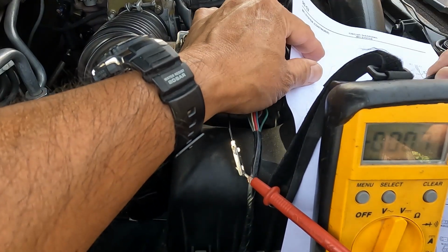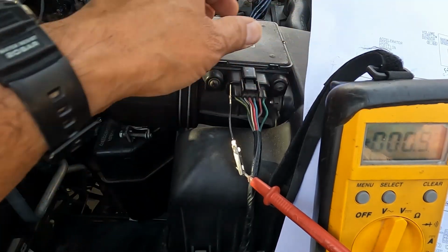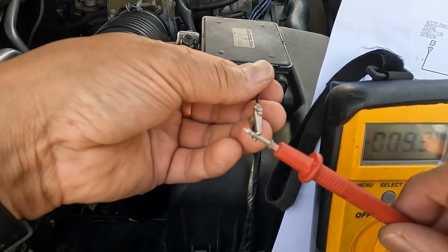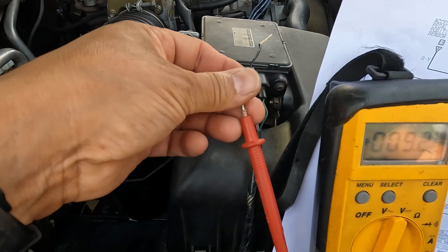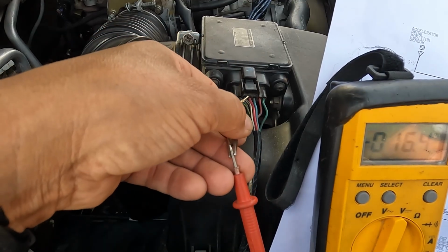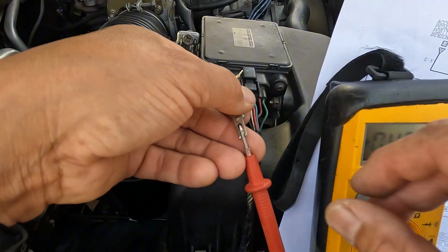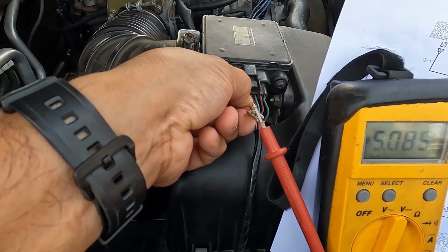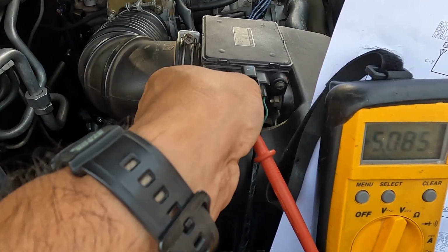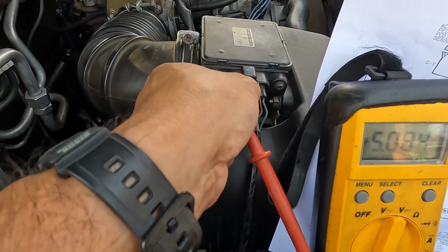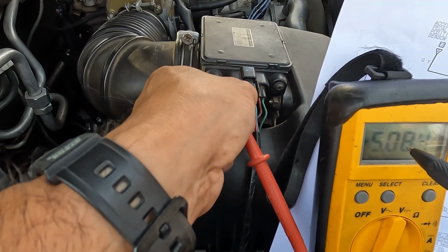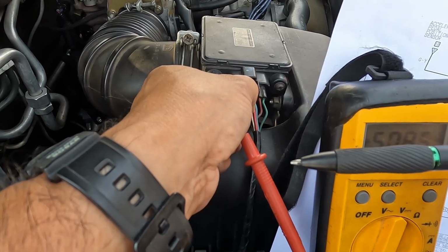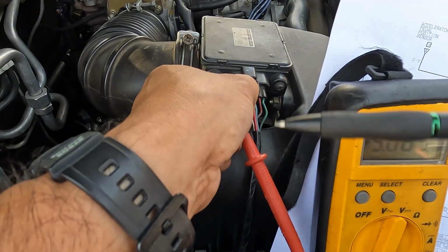The baro, we had said we had 4.0, and we'll go over these on the bench over there. So those are the first 5. Now these are the signal, the mass airflow sensor signal wires. Terminal number 3, which is the white with the black stripe, and that one, remember when I told you guys that's a frequency output signal. So we're expecting 2.5 volts on that, but we have 5.0 volts. Okay, so it should not be 5.0. That means there's no signal coming from the sensor back to the computer, but it does have the 5 volts going from the computer to the sensor.